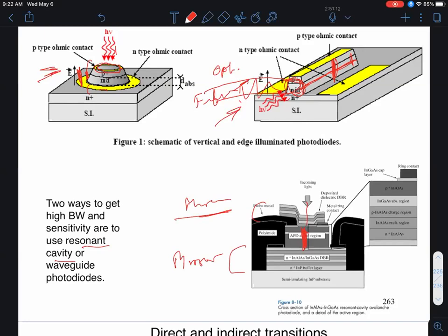Now these mirrors are a special type of mirror. They're made up of thin layers of two different dielectrics or two different semiconductors with different refractive indices. Those are known as Bragg mirrors, okay? After a physicist, Bragg. I won't go into the physics of that, but basically, if you have a periodic structure of refractive indices, by designing the thicknesses of these layers and the corresponding refractive indices, you can adjust what's called the optical length.